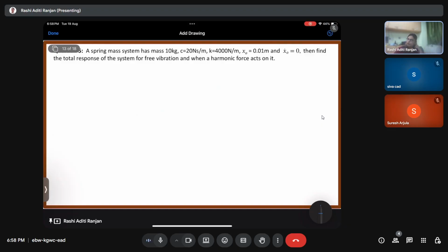This type of impact loading related solution that we are finding is actually helpful for us in order to find out some properties of the system. For example, if I have a system that has some mass and it has some stiffness, and I don't know what is going to be the damping value, what I can do is impact testing. I'm going to get the response of the system with that impact testing, and from that response I can find out the value of eta.